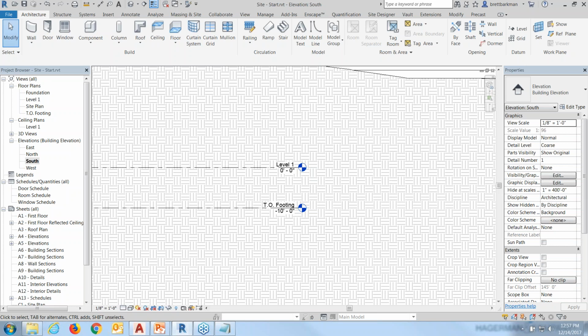But it is possible, depending on where your survey point and your project base point are. You just make sure that those don't move in between your extractions if you happen to be doing more than one. So I hope that helps. But there is a potential there, I would say. You just have to do some checking after you bring each data set in and see if anything is out of alignment. If it is, then at least then you'll know.